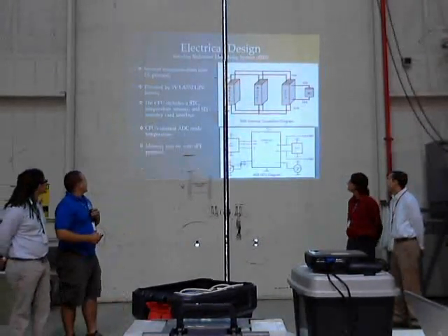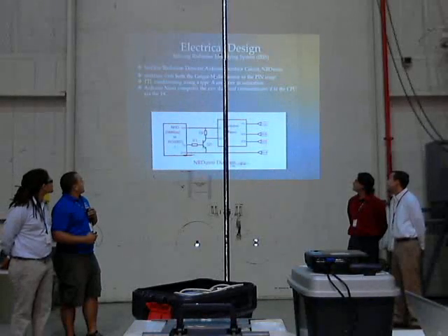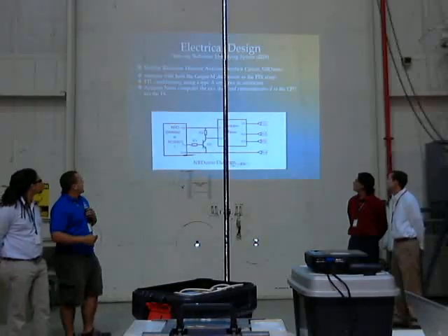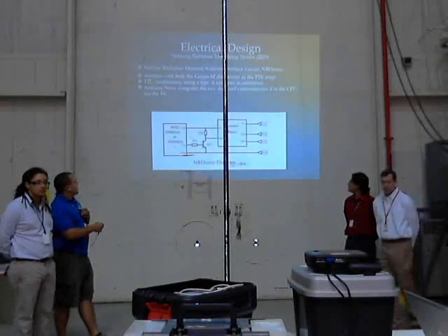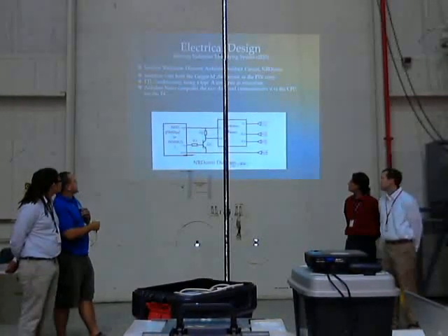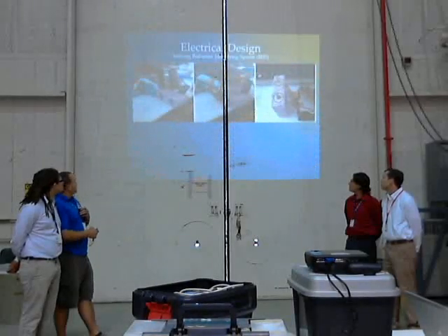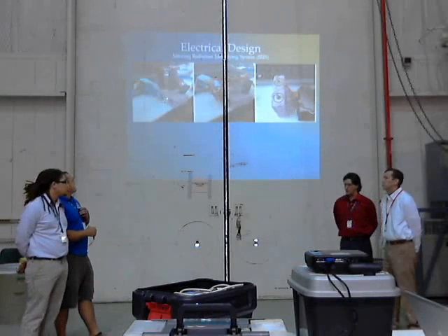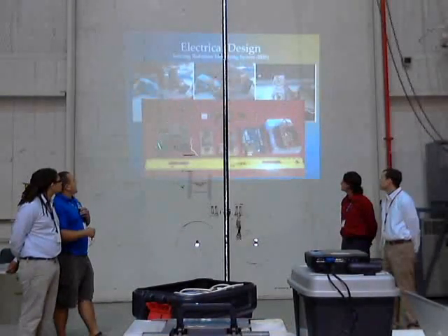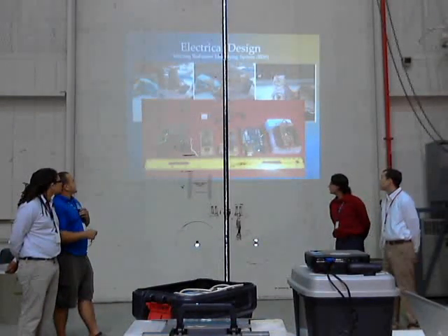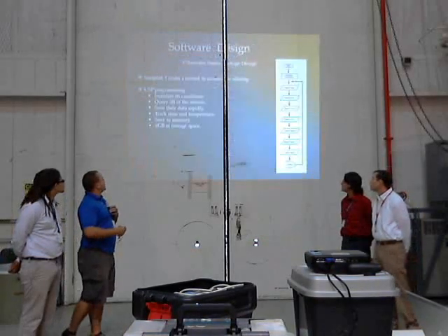Gotcha. All right. Electrical design for the sensor interface. I designed a circuit to interface the sensors over the I2C bus, in which case we have a transducing circuit. The circuit is designed to work with either sensor interchangeably. Here we have a picture of the sensors. Up here we have the Geiger tubes. I encased them in foam for protection, and we also see the PIN diode array. This is a picture of the whole system taken apart. This case holds the data logging shield, the two Arduinos, and the Geiger-Müller tube.